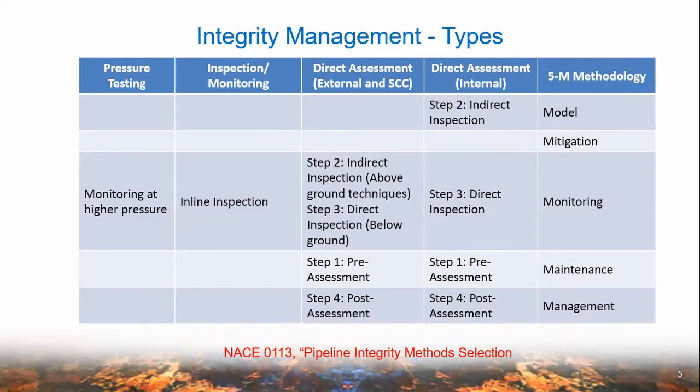Third, we monitor the pipeline once in a while to ensure that the pipeline is behaving in the manner in which the model has predicted, or to ensure that the mitigation strategies implemented are working properly. Fourth one, we carry out maintenance activities as required, just like we take the car to the auto shop once in a while for service.